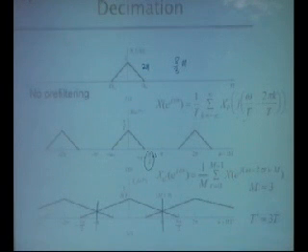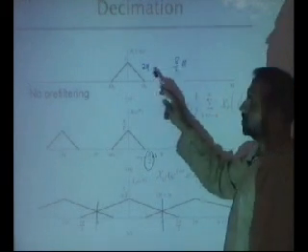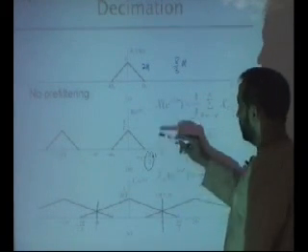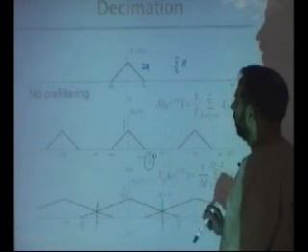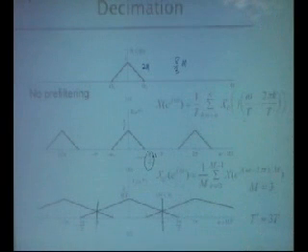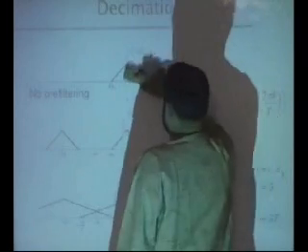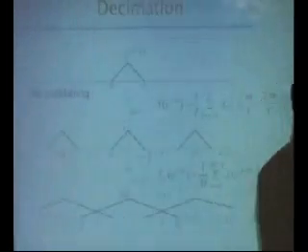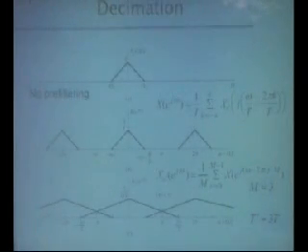So you are sampling it at 8 by 3 megahertz, and you are not obeying the Nyquist sampling criterion, which says you sample at least at 4 megahertz. If you do this, it obviously is going to corrupt your spectrum. So we must not do this.